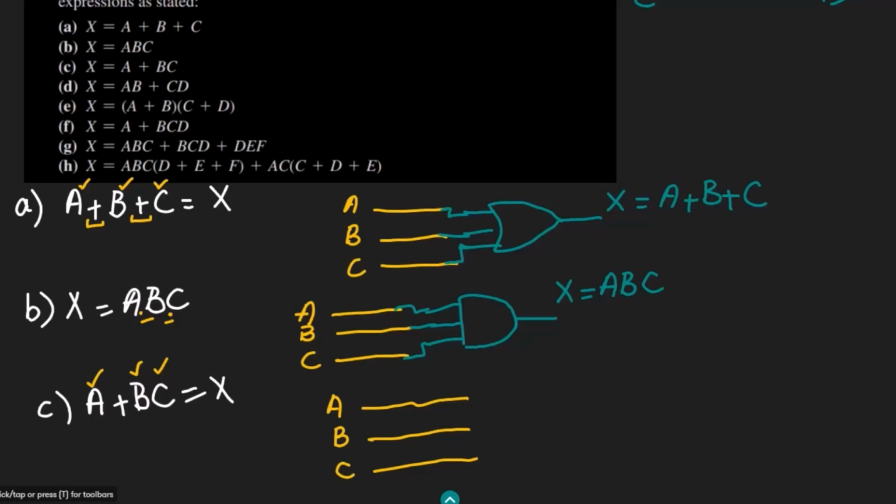And what has been happening here, we can very easily see that first B and C are multiplied together, and then these are added with this A. Okay, so first of all these two will be multiplied together and then added with this A. So therefore we will have 2 gates here, the AND gate. Okay, and this will be what? This will be the OR gate. So therefore let me draw them. So the AND gate is between B and C, so this will be the AND gate.